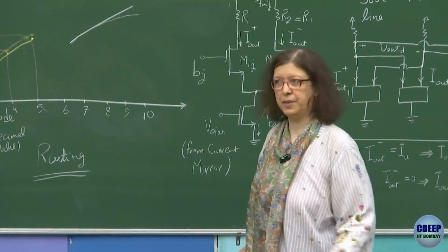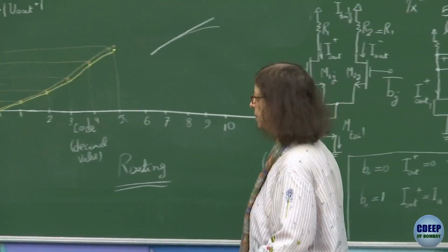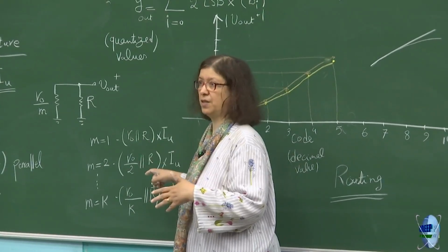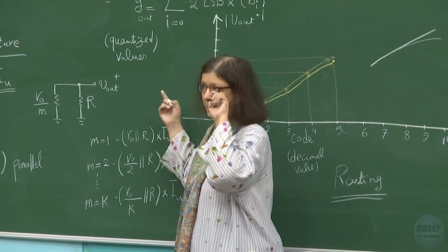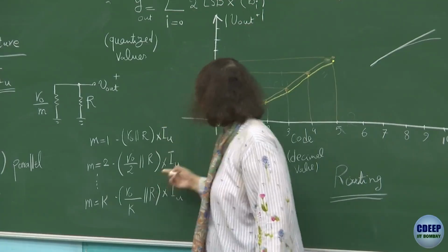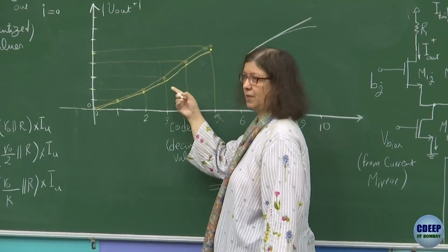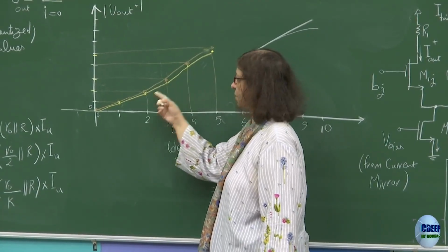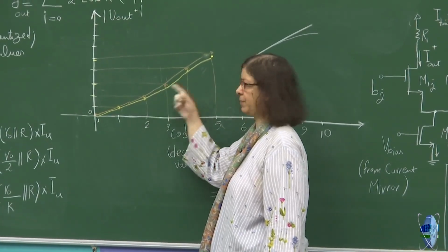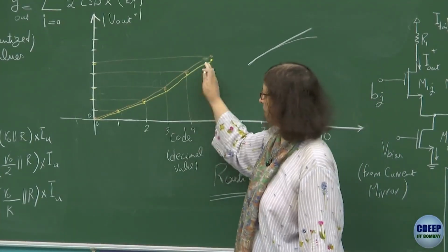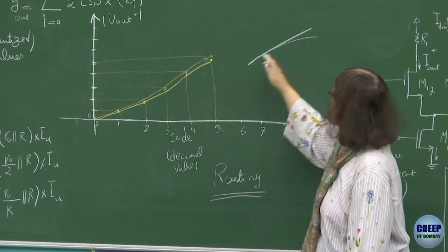No, not necessarily. That is exactly the point. This is okay for a low number of bits. What you say is manageable, because this error is one of n reasons for distortion and eventually INL/DNL error. This nicely shows the INL, right? It shows how the switching points of this characteristic are changing. So it's a representation of INL or distortion in the characteristic, so that instead of a line we have a curve which is also bending.